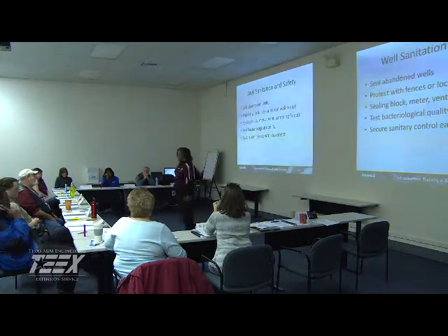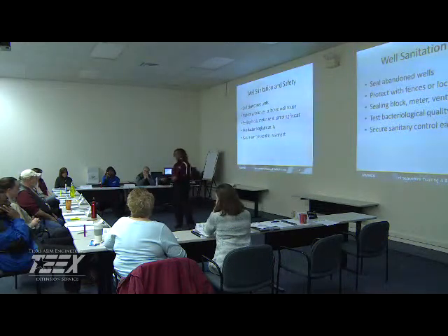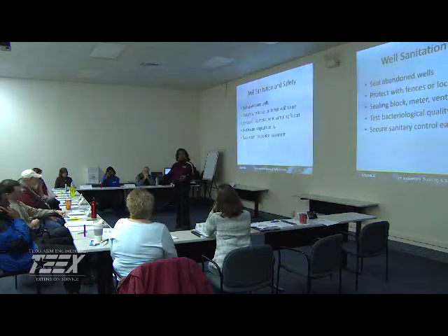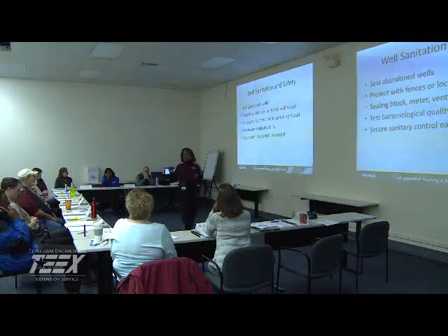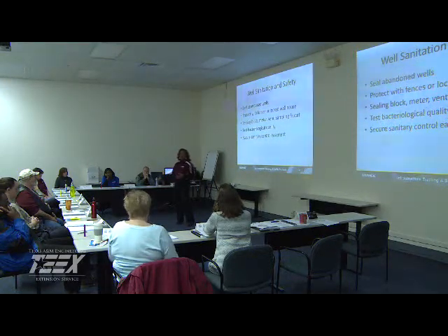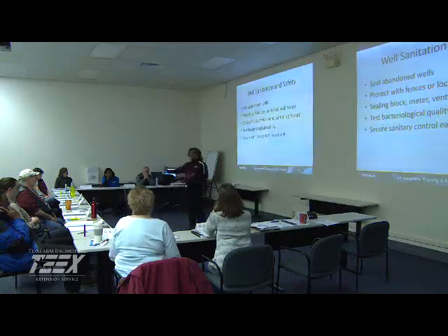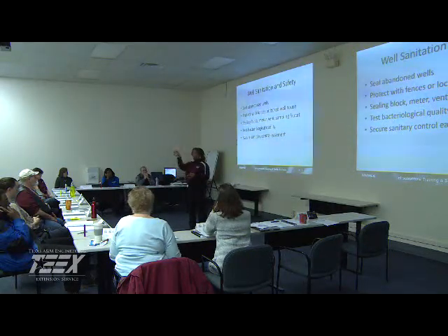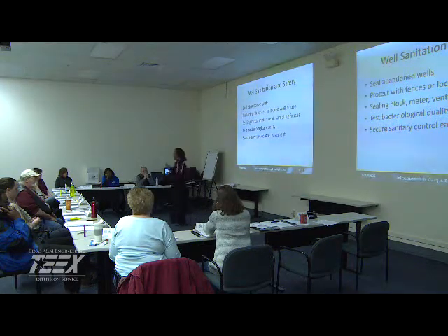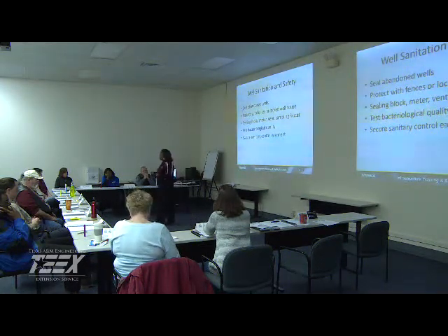It probably does. And keep in mind, what we're trying to do is ensure that what we've put in, the well is properly disinfected, by allowing it to run for that long. We do that with our chemical and physical analysis, because now I want to know what's representative of the water that's in the aquifer. Maybe that's the stance they're taking also, checking the water in the aquifer as opposed to the well itself. I'm not sure. But I know on our chemical and physical, it's after 36 hours of continuous pumping.